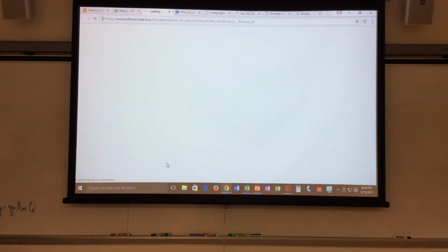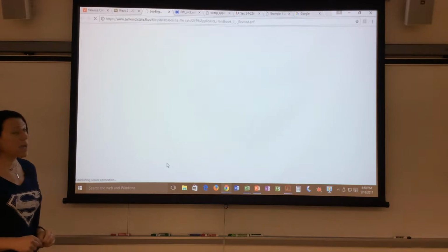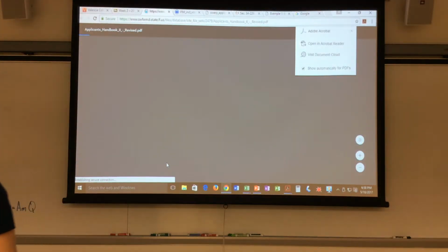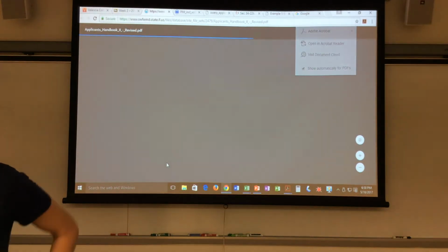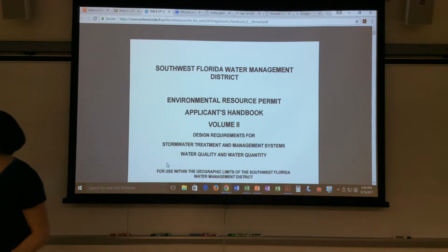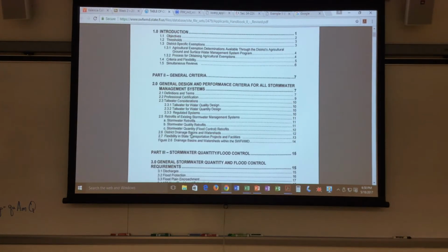And then you've got Southwest Florida Water Management District. And these are all available online. So when you start as an engineer or a designer, you need to look all of this up so you know what to design by, because you don't want to design by the wrong storm event and figure out the discharge rate that you picked and designed for your control structure doesn't work.